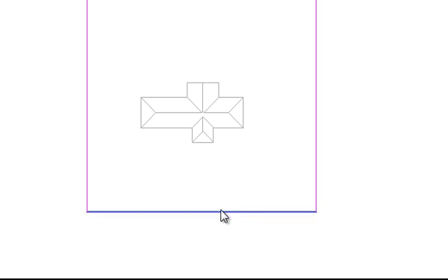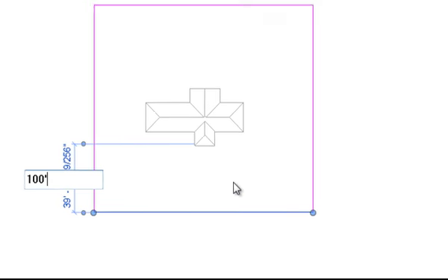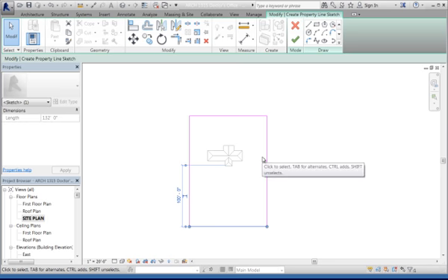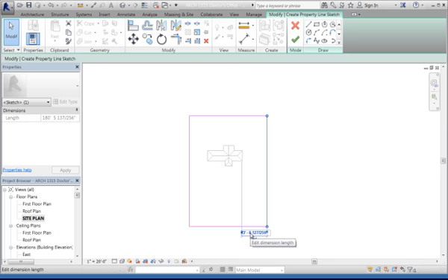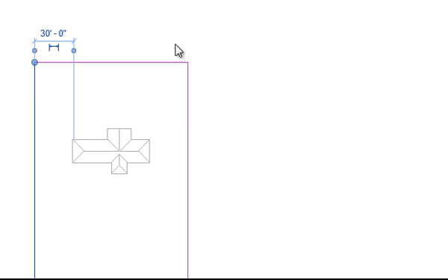And then I want to make sure that my front, see, it's only 39 feet, so I need to change that to 100 feet from the front. So it's going to go way down there. And then I want to make sure my sides are at least 30 feet. And you can make them more. They just can't be any less than that. This side is going to be 30 feet. You may have to make it more with parking.